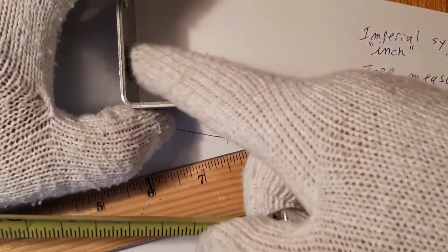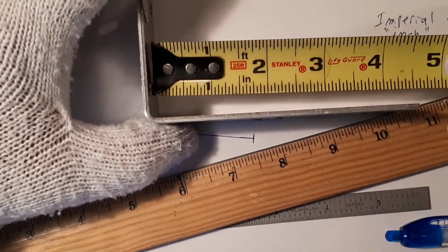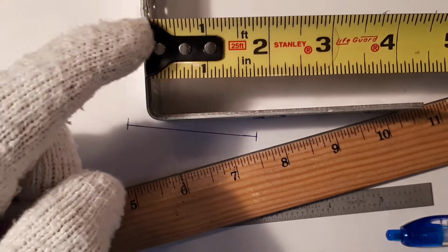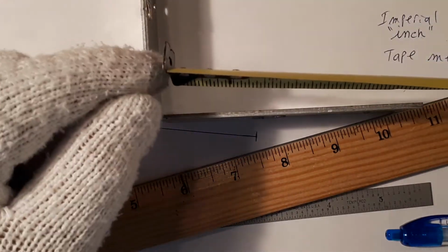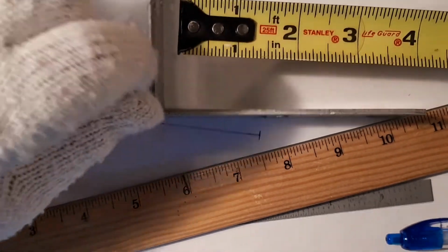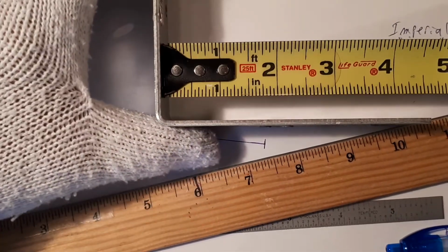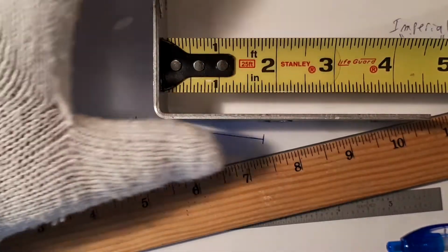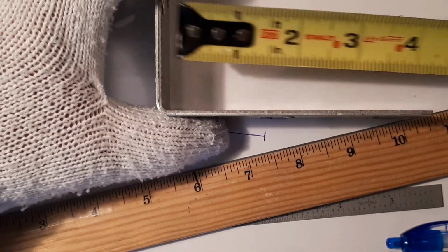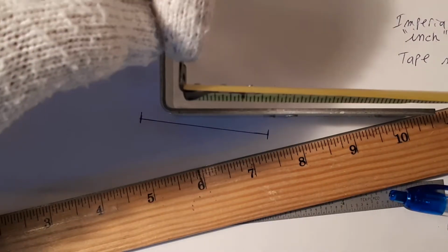If I wanted to make a measurement on this surface, I place the tape measure against that surface and push in. When I push in, the tape measure moves inward the thickness of that tab. And now the 0 is here. This now becomes the 0. And so I can make a measurement, 0, 1/16, 2/16, etc., going all the way down. So this is designed to go both ways. When I pull on it, it extends outward, and when I want to measure on the inside, it moves inward, such that the 0 changes from that surface to the other surface.